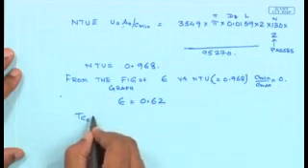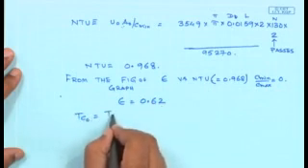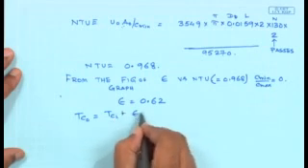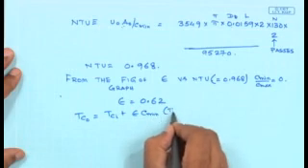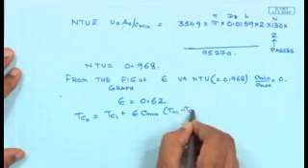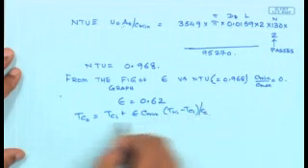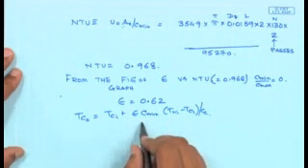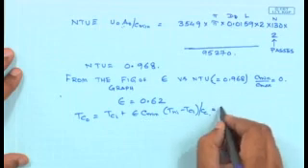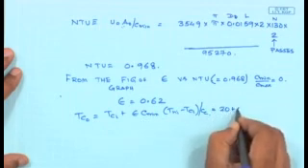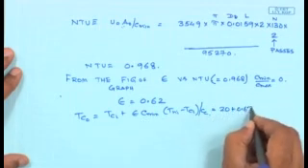So the next part is straightforward. TCO is TCI plus epsilon C minimum by CC times THI minus TCI. This is just the definition of epsilon over here. So when you put the values in here, this will be 20 plus 0.62